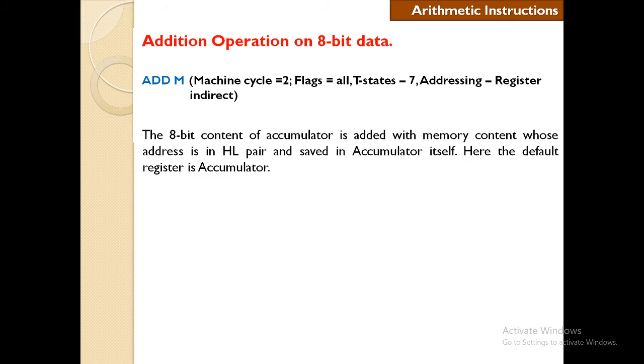Now let's see, the 8-bit content of accumulator is added with the memory content whose address is in the HL pair, and the result will be saved in accumulator. So again the default register here is accumulator. Now let's see with an example.